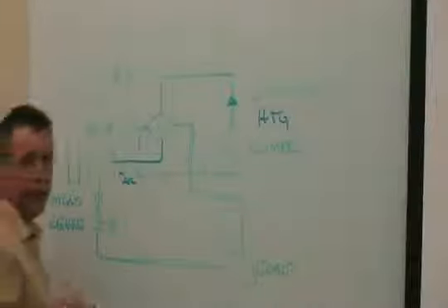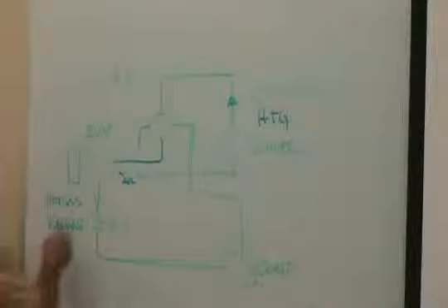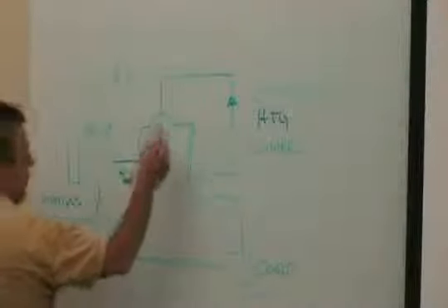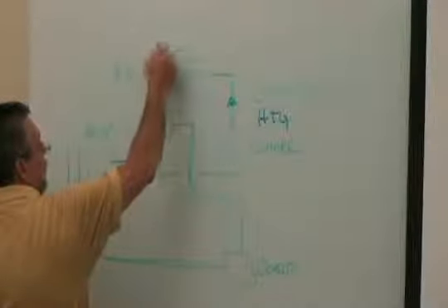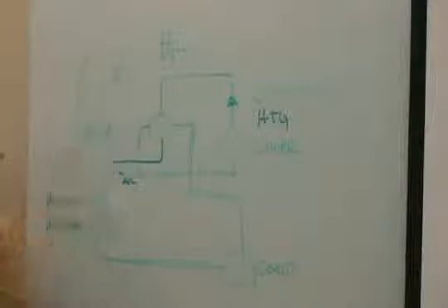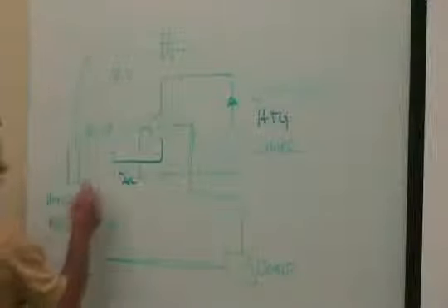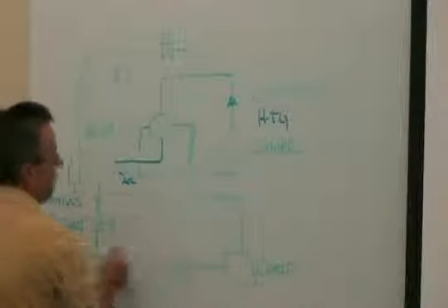So there's not any cooling demand other than drying out the outside air. So I introduce hot gas, then I introduce another valve here that puts the hot gas back into this, and then we go back into our suction line from the hot gas.